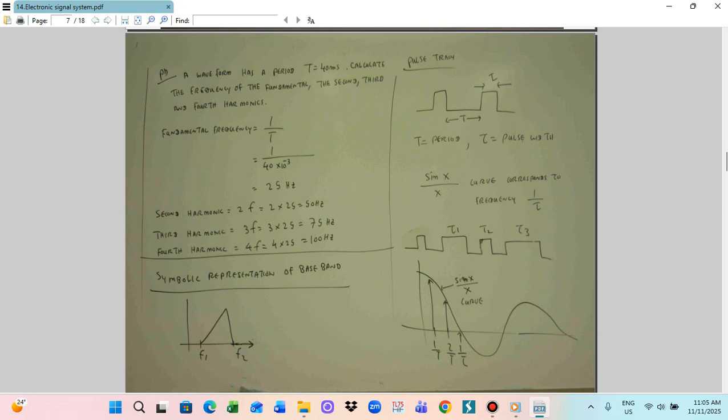We also have to know about transmission bandwidth. Bandwidth means the range of frequencies where the signal power spectrum is significant. This is important for the system bandwidth. In this case, a specific band needs to be passed through by the system, so we have to utilize the bandpass filter. A bandpass filter works between the minimum and the maximum frequency, so a specific band of frequencies is allowed to pass through.